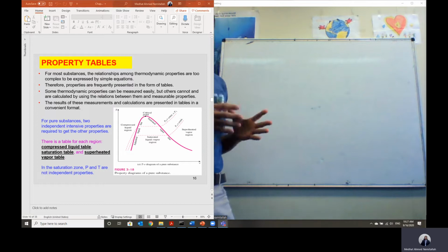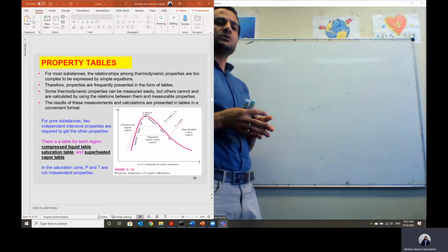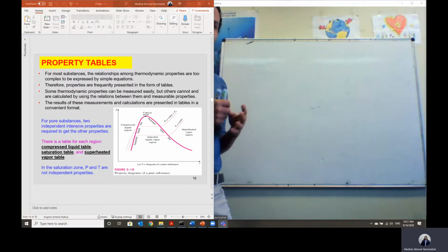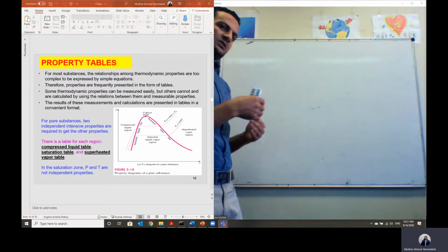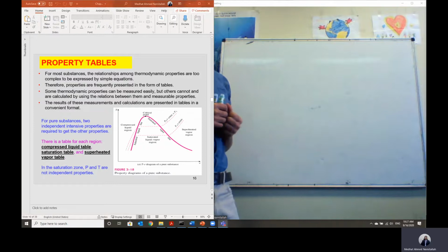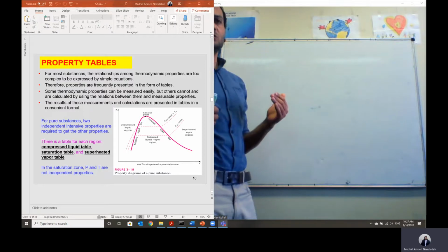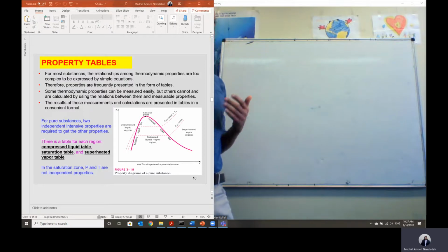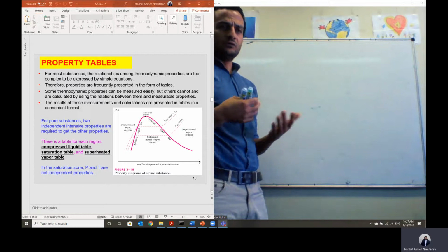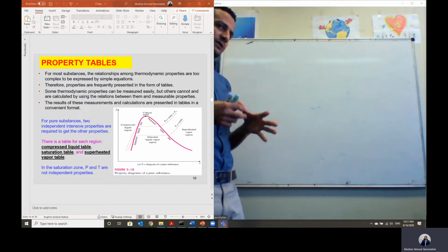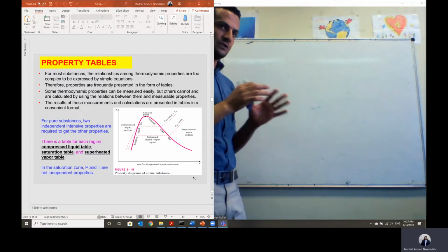Those refrigeration systems work using freon or refrigerant. This freon is a fluid with very low saturation temperature, so when it is passed through a system, it can absorb the heat. On the other hand, it consumes work, electrical power to run an electric motor. This electric motor runs a compressor to compress the freon through the cycle.